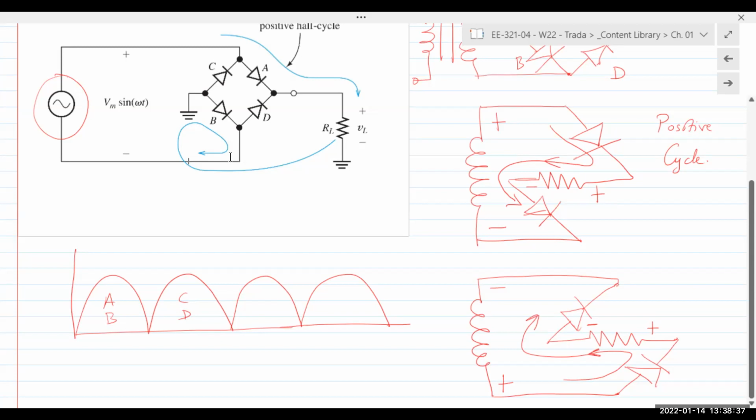So in the same sense, if it shows you ground here and ground here, it means these points are connected together. This is especially true of ground, right? There will be multiple points in a circuit that are all connected to ground. And so if it's far apart in the schematic, they just draw it separately. And the reason I draw it this way is because it makes it easier to explain how it is.